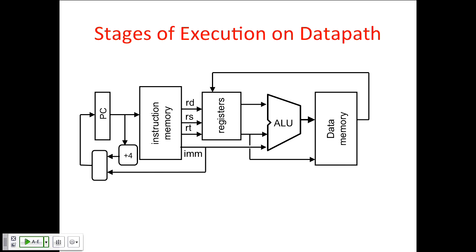So notice you have the program counter at the front here. And the first stage is instruction fetch, where you take the value in the program counter and send it to the instruction memory. And by send it to the memory, I don't mean you put it in an envelope and address it. There's a set of wires that carry ones and zeros. So the ones and zeros coming out of the program counter, at the clock edge, you'll update the program counter. There'll be new values of ones and zeros. Those will change the values on those signals going to the memory. The read of the memory is also a combinational process. So after the inputs settle down to the memory, sometime later, this instruction memory is going to produce an instruction at its output.